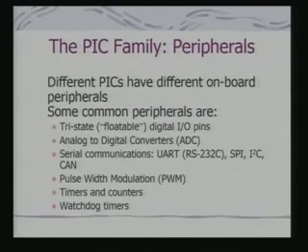The more common peripherals on this PIC microcontroller family are digital I/O ports, analog to digital converters, serial communication interfaces like UART, SPI, I2C as well as CAN interface, pulse width modulation module, timers and counters, and definitely watchdog timer.